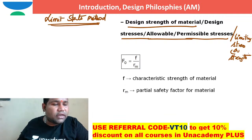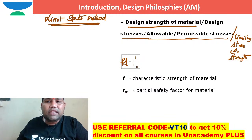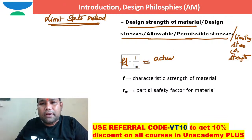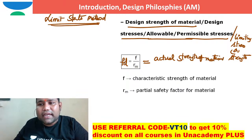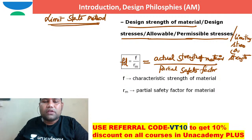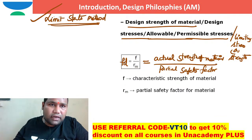How can we find that design strength of the material? If ft is the design strength of the material, it is equal to the actual strength of the material divided by the factor of safety. Actual strength of the material is nothing but the characteristic strength of the material divided by the partial safety factor for material. These partial safety factors for material I need to consider as per the limit state method.